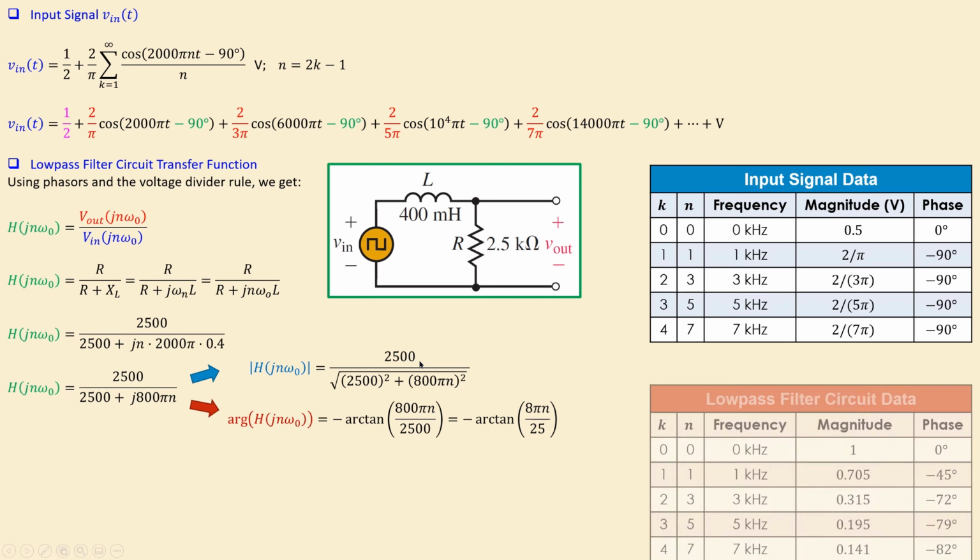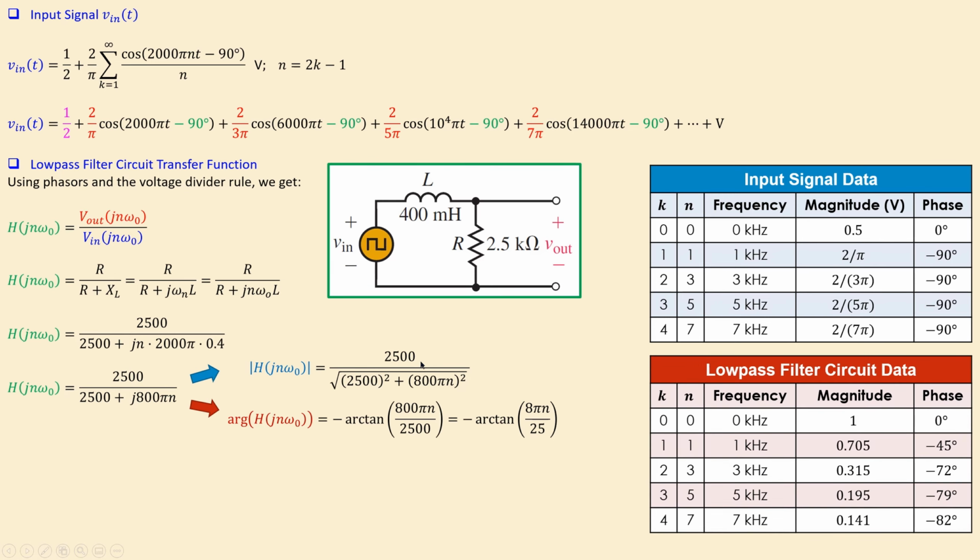Now, if you collect the terms again for cases 0, 1, 2, 3, 4, etc., and also for the associated values of n using this formula, you can see all the exact same frequencies: DC, fundamental, first, second harmonic, third harmonic, fifth harmonic, and seventh harmonic. These are the values. If you do the math here, for n equal to 0, this is just 1 for the magnitude.